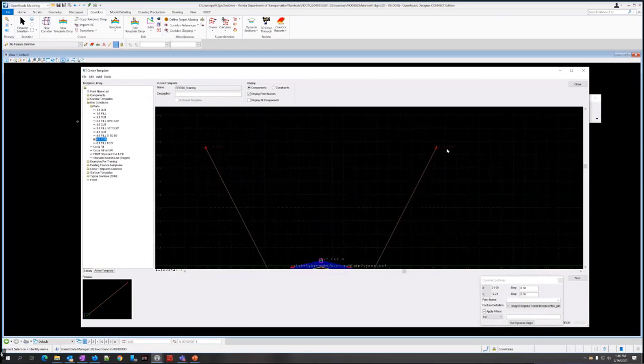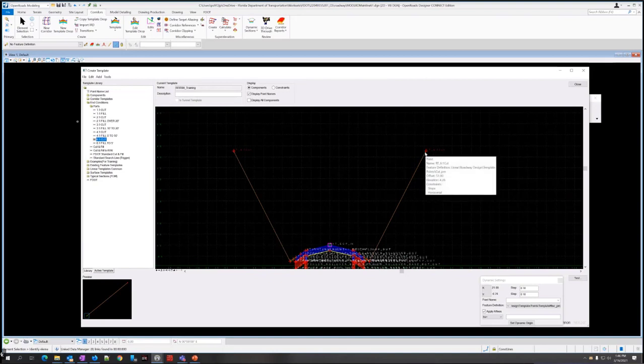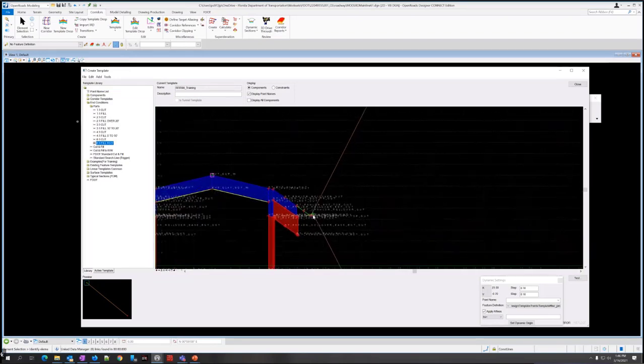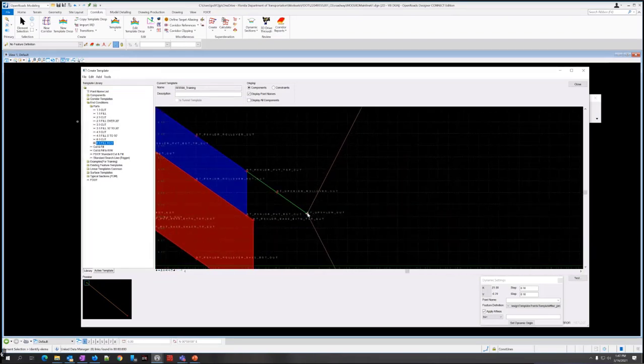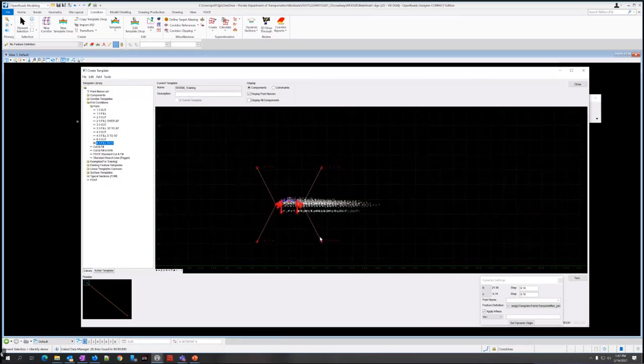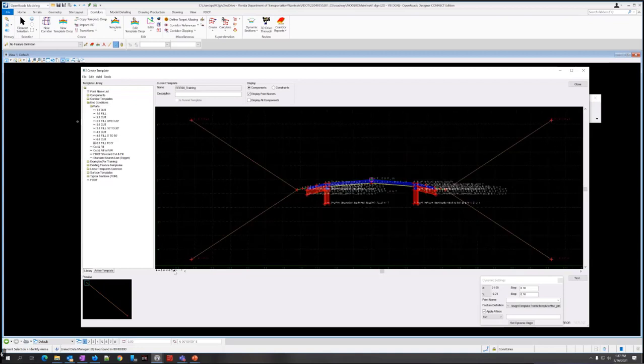So we have right 6:1 cut. And this is left 6:1 cut. That's good. So we need to fill 6:1, fill to 5 feet. So I'm just going to drag that in over to the right side. Same point. Snap it to there. All right, so we've got cut and fill options. Let me just get the view so it looks a little better. And I'm just going to come over here and do File Save. Save my changes.